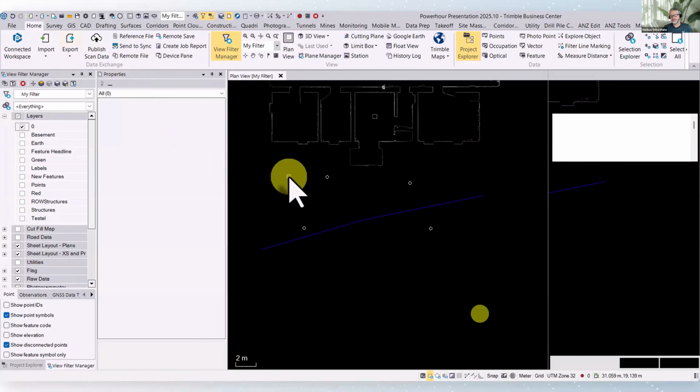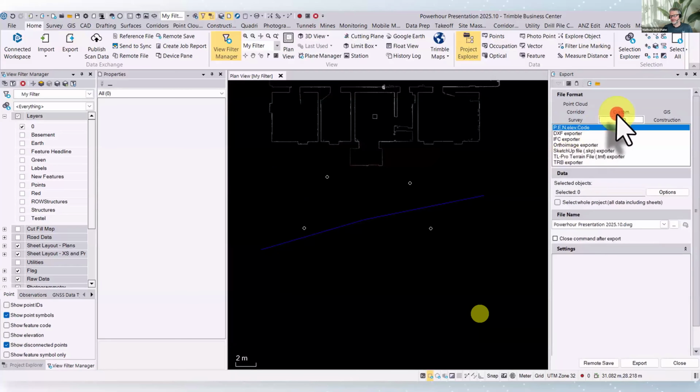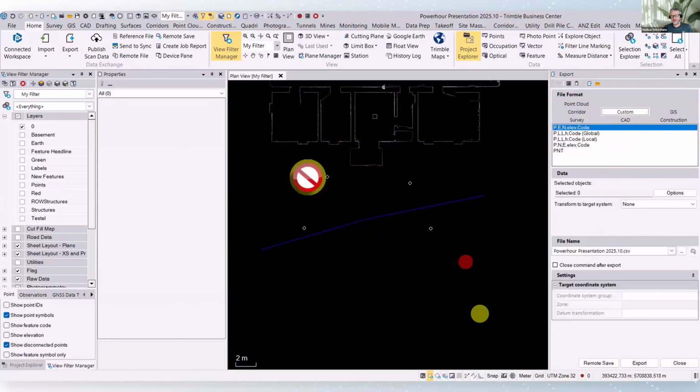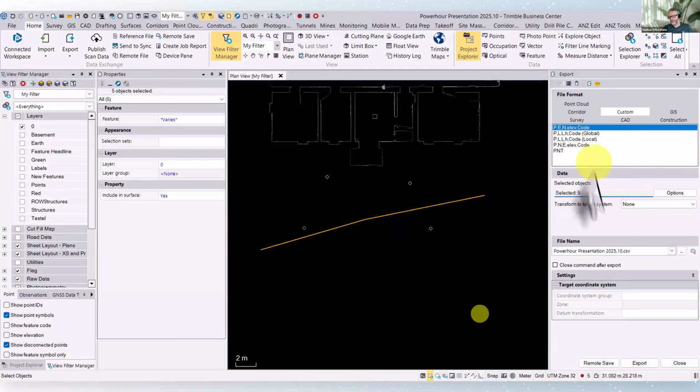And then to custom exports, and I select some points. Here they are. And now I apply that decision. What do I want to change? None, local, or CRS. First export will be with none, no transformation. So we are here now in Europe within a UTM coordinate system. So I call this CSV file UTM CSV, export it.